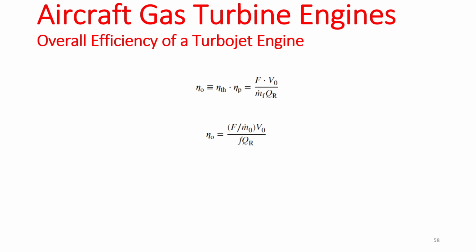We can, of course, play with this a little bit. We can divide everything by m dot naught, which is your mass flow rate of air. In the numerator, you're going to get F divided by m dot naught multiplied by V naught. And what does this stand for? What is F divided by m dot naught? It is the specific thrust, exactly.